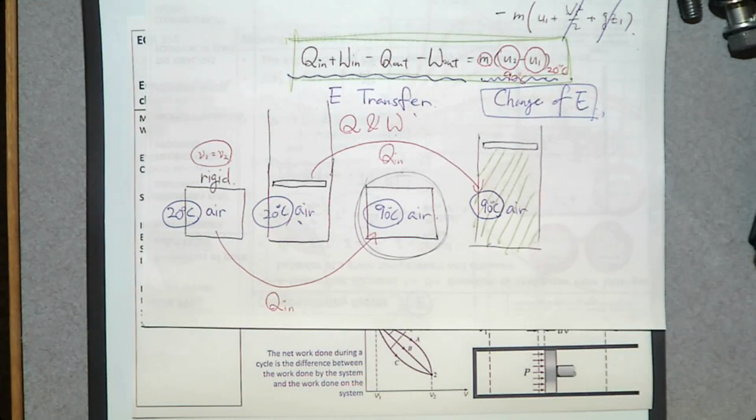We can, right? Because then why is there a difference in the total energy? Because there is more work because of this air expansion. So the piston was here, and this air pushes this piston upward. So more work is done on the system. So the total energy of the system here should be greater than the total energy here. But this energy balance equation cannot explain the difference.